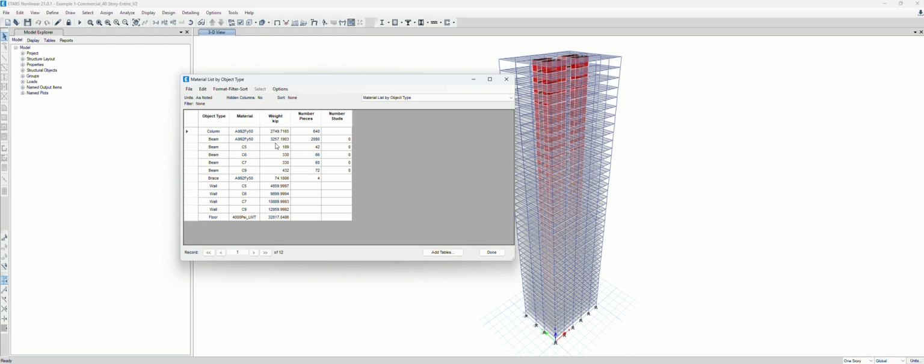As opposed to steel, for the concrete we are getting the total weight in kips, but obviously we always use a volume of concrete because this is something the industry values. To estimate total volume, you can just sum up all the weight in kips, divide by 150 pounds per cubic foot, so that you can convert that to cubic feet. That is an easy conversion.